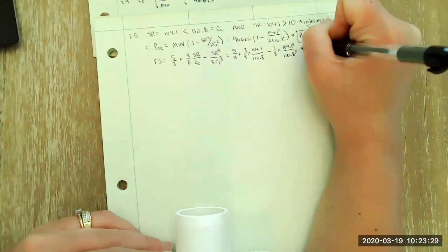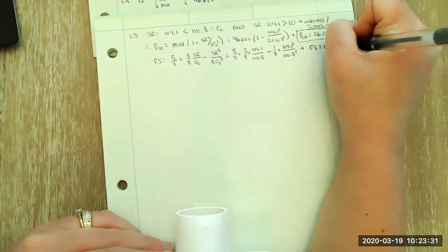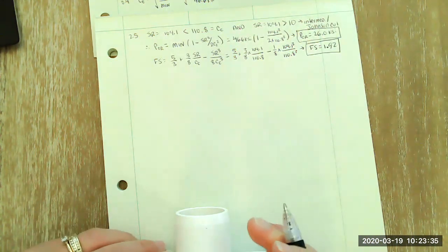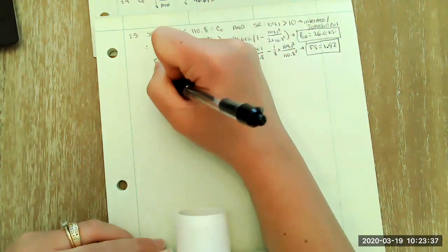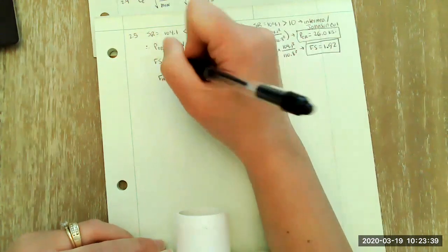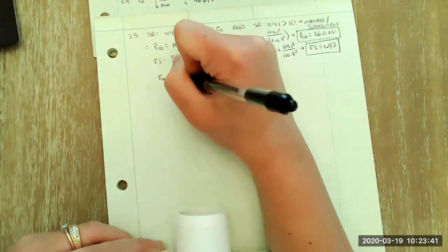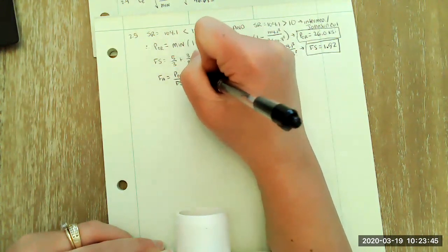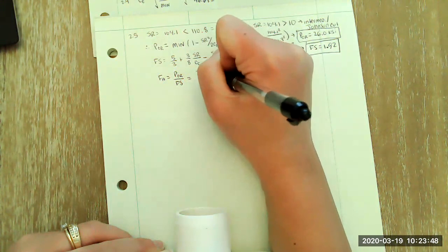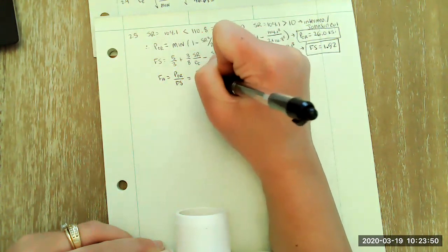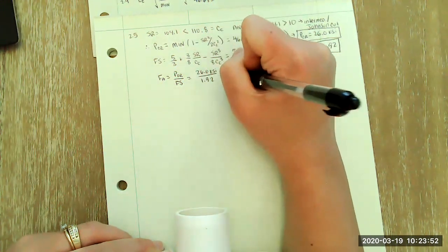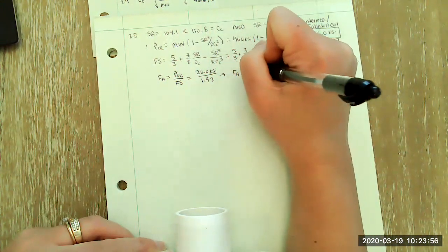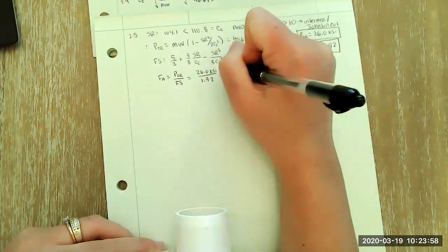And so our factor of safety is equal to 1.92. Pretty reasonable value. And finally, our allowable stress is equal to P sub CR divided by our factor of safety, which is 26.0 KSI over 1.92. So our allowable axial stress is equal to 13.5 KSI.